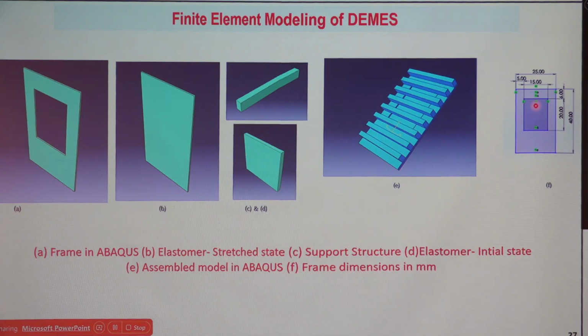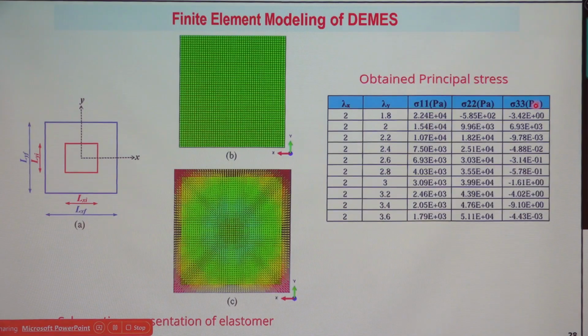Okay. Any doubt till now? So the important step is how to give pre-stress to the membrane. This is again a very important task. So there are two different ways in Abaqus. So what is happening after assembly, if you give the pre-stress to the membrane that I have discussed with you, the membrane is now clubbed with the frame and the stiffener is already attached. So now if you try to give pre-stress only to the membrane, it is not going to get effectively implemented on that.